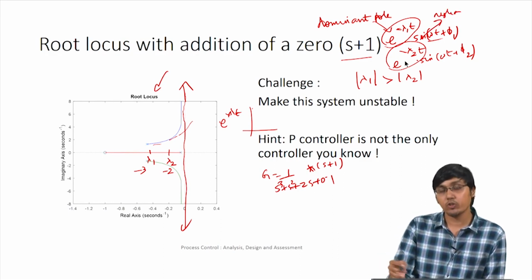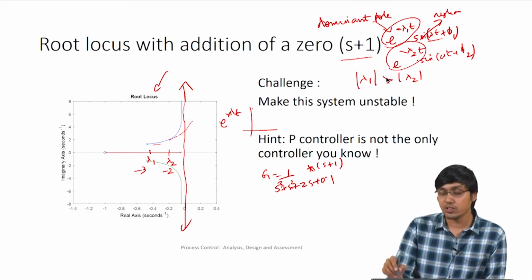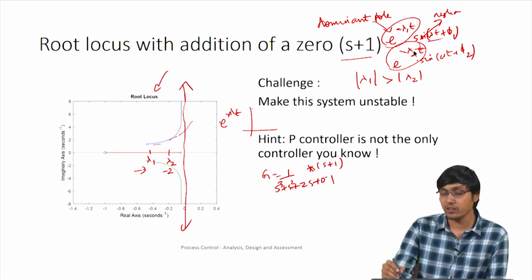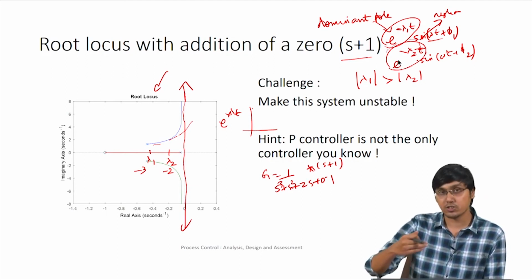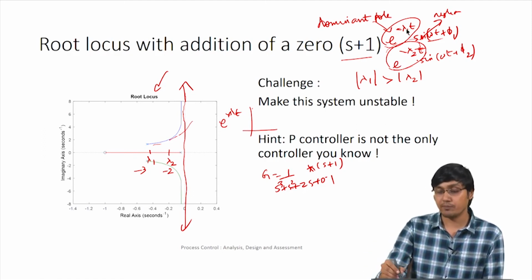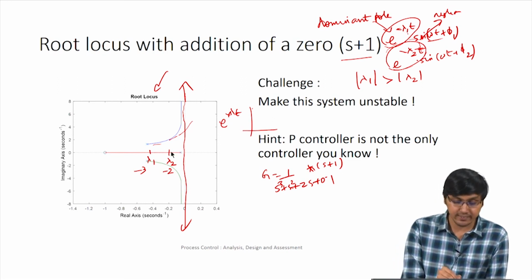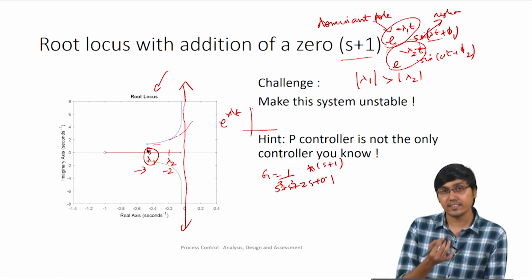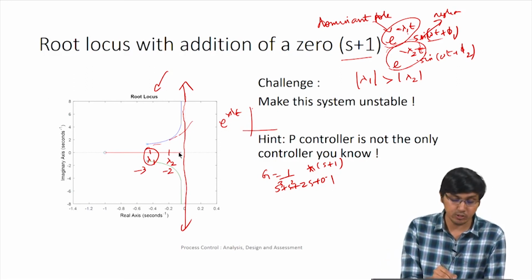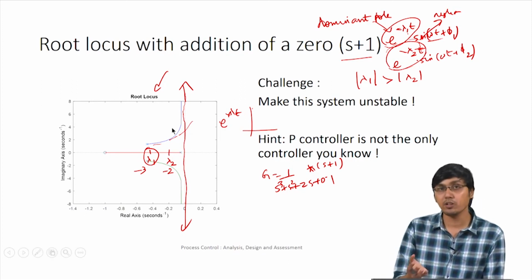You can plot these two values for the same time and see in MATLAB how it's responding. That is one way to do it, but we can easily see from the math, or by intuition, that this particular term is going to decrease slower, and this particular term is going to fall faster because lambda 1 is greater than lambda 2. So this pole is not causing a bigger impact in comparison to lambda 2. So lambda 2 is a dominant pole compared to lambda 1.